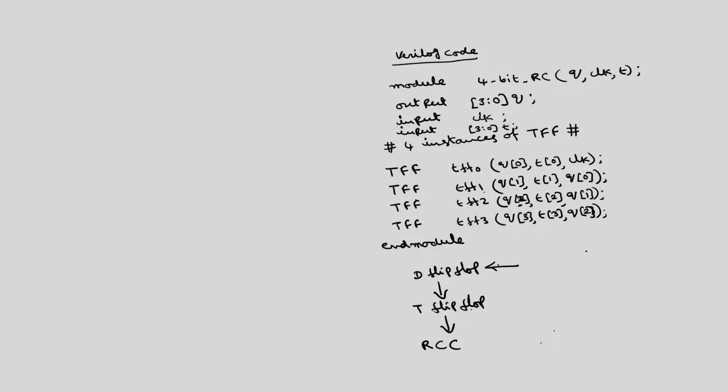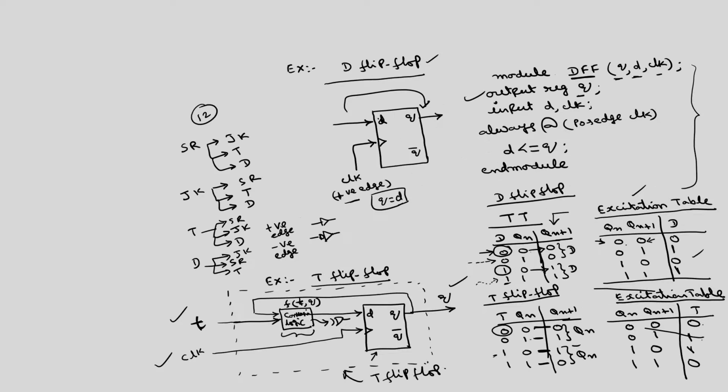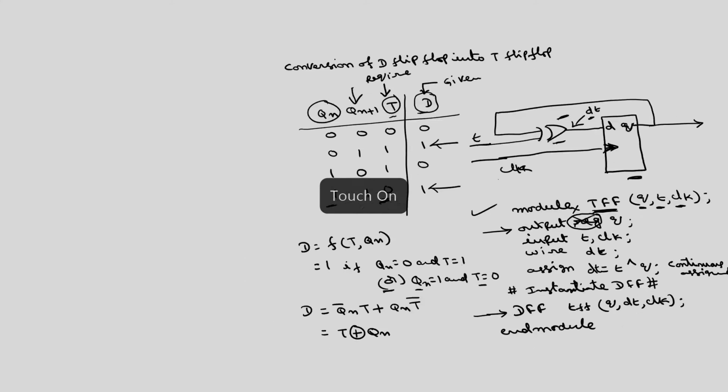In the main program of the D flip flop, the operation is very simple. We can write the code for the D flip flop by simply assigning Q equal to D, but this is not the case for a JK flip flop. In a JK flip flop, we cannot define the output simply as Q or Q0 or Q0 bar. It has to follow a truth table. So, how do we write the Verilog code for the JK flip flop?